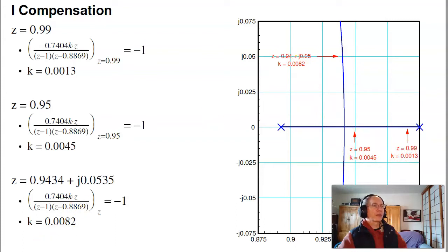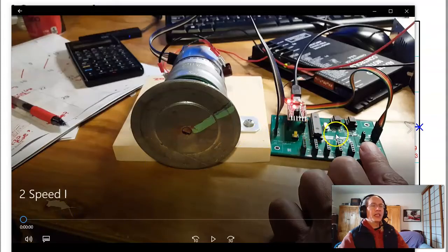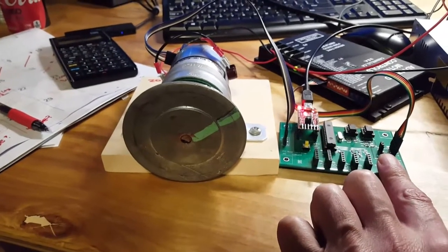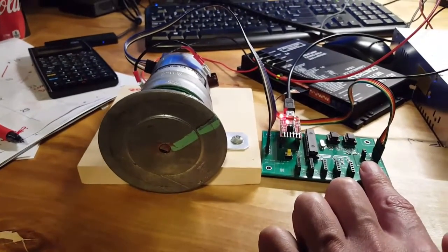And to show you what that looks like, here I implemented this in hardware, so this actually has the integrator built in. This is with a pole at 0.99. As I change the set point, when I hit this button here, I change the set point from 0 to 50. I'll be integrating up, changing the speed. This is an example of integral feedback.